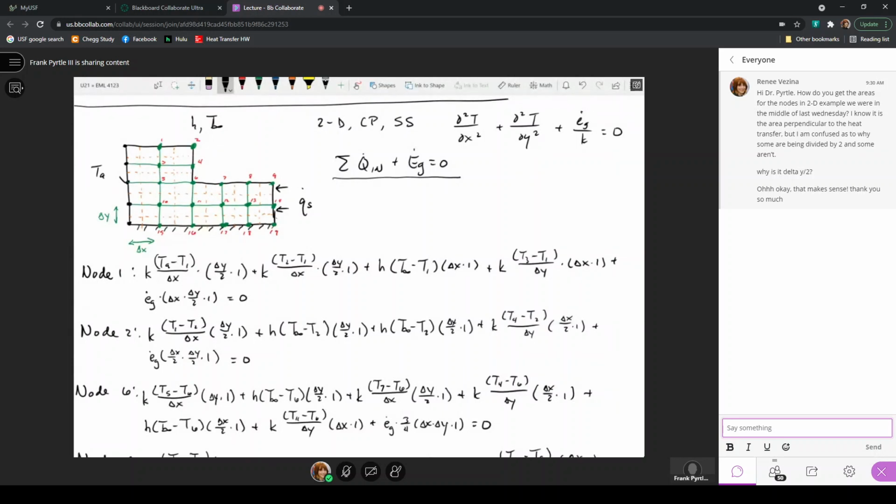Now, if I wanted to calculate, once I have the temperatures here on the top surface for nodes 1, 2, 4, 6, 7, 8, and 9, these temperatures will all actually be higher than T infinity. So if you were asked, what is the heat flux out of this top surface by convection? Well, I know that the temperature across this boundary is a temperature that is TA, because this node is representative of this temperature for this entire 1/4 of a block.